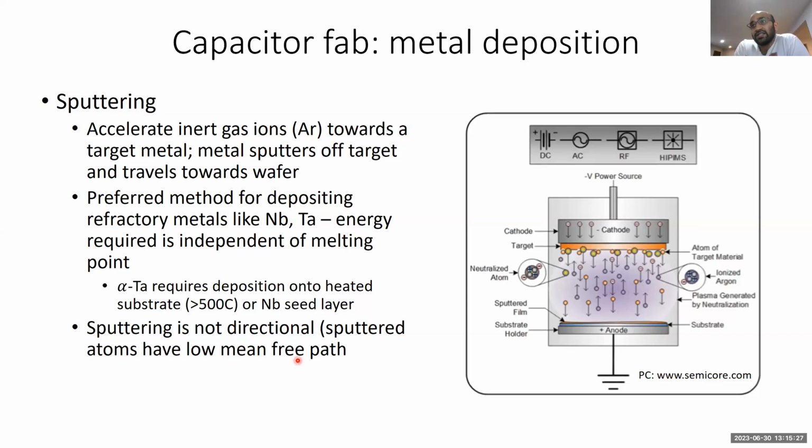And because we do these high temperature processes, we really don't want to deposit aluminum in a chamber that we're heating up to above 500 degrees. So we generally like to keep those processes separate. But I have heard of other groups that do sputter aluminum. The question about which is better when it comes to aluminum, I'm really not sure. I don't know if there's been a systematic study that has looked at that.